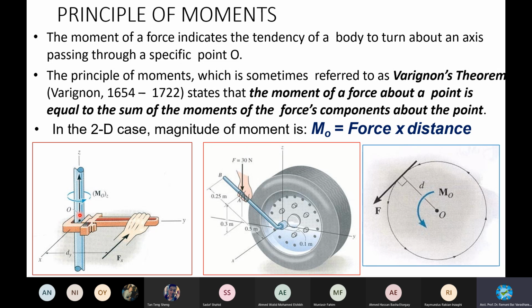This is the point where you need the job done, the focal point, and you are applying the force here. When you apply the force, it will be different. Why? Anybody? Derek? The force is applied here. All of you know that the moment about this point, how much couple you have to apply, is given by this force times the distance from this point, isn't it? The moment to be applied to rotate this is force into this horizontal, perpendicular distance about this axis, so that it can rotate, remove or fix.